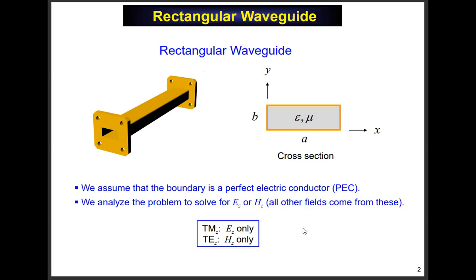Now, you cannot have in a hollow pipe of metal anything that looks like a transmission line mode, like a coax mode. Remember, that's a TEM mode. I'm not giving a rigorous mathematical proof of it, but any TEM transmission line wave requires two conductors. They can be running side by side like a twin lead. One could be inside the other like a coax. But you have to have two conductors. That's what a transmission line is. That's what a TEMZ wave is.